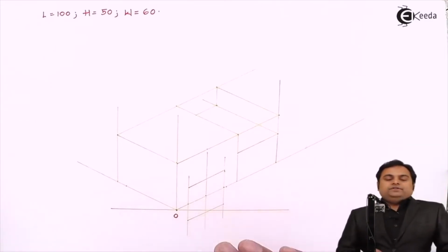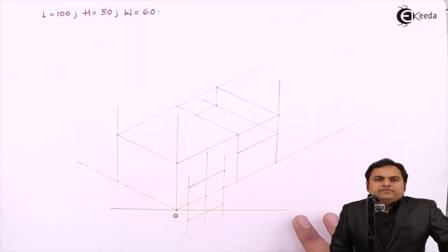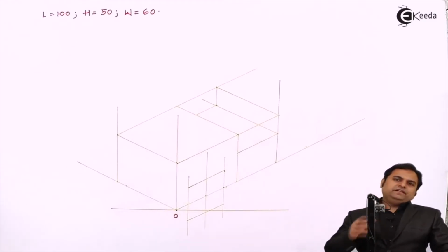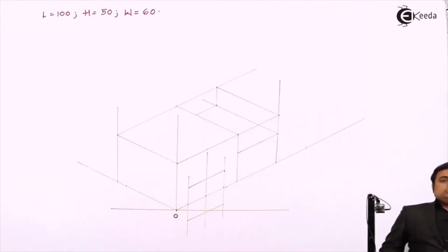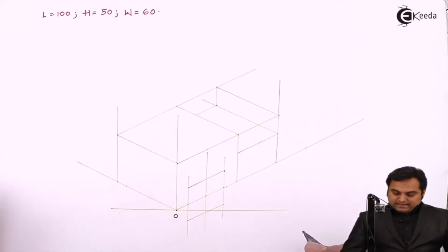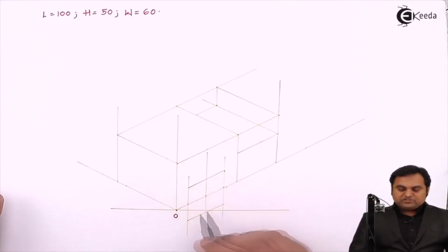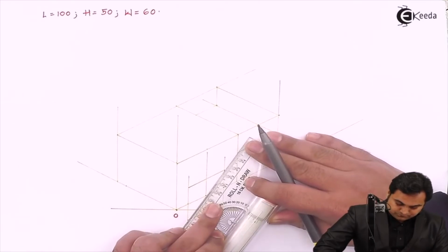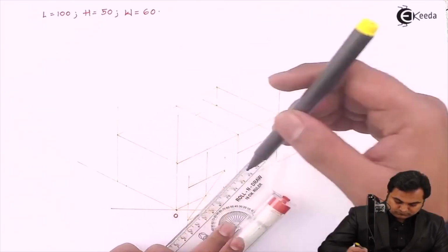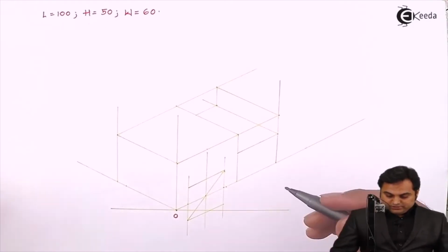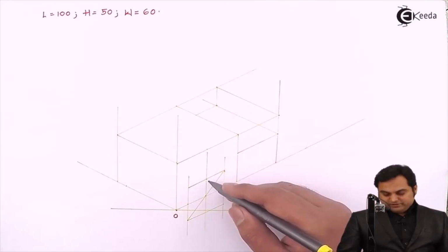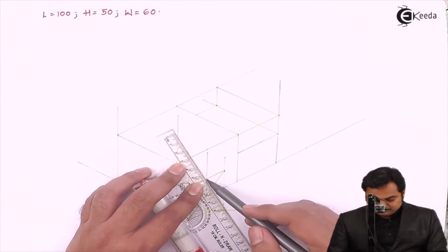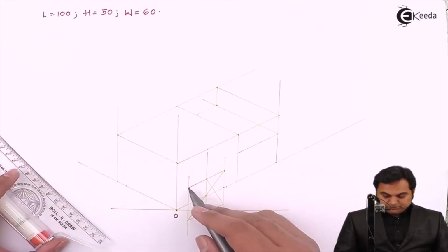So this is the parallelogram, and here I am explaining the method, that is how to draw a semicircle if it is an isometric drawing, because here we cannot take the radius or diameter directly and draw the semicircle because the surfaces are inclined. So that semicircle will also be inclined, and for that the procedure is, after drawing this parallelogram which is having sides equal to the diameter, I would be drawing the longer diagonal here. Next, after joining the longer diagonal, here I have the top midpoint. So this top midpoint will be connected to its opposite bottom corner. So I'm connecting it with the help of light line. Then bottom midpoint to the opposite top corner.